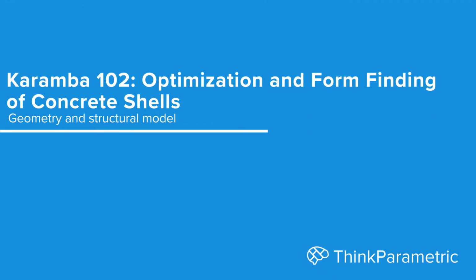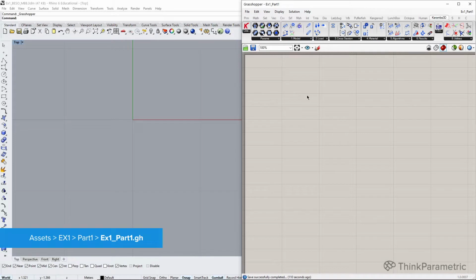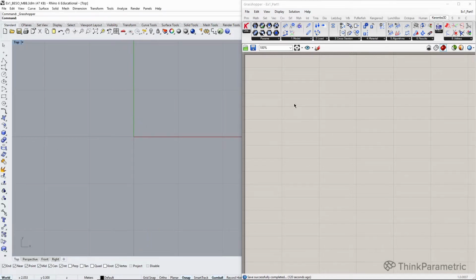In this exercise, we'll topologically optimize a simple supported beam using bidirectional evolutionary structural optimization. Okay, let's get started. Just to remind you, we work with meters in Rhino, and firstly we need to create our initial domain that is simply a rectangle.